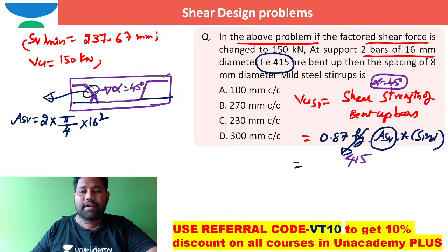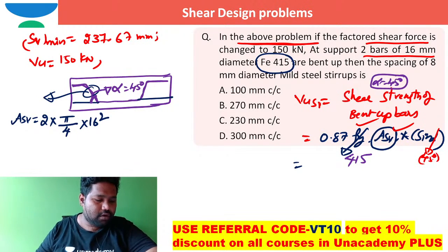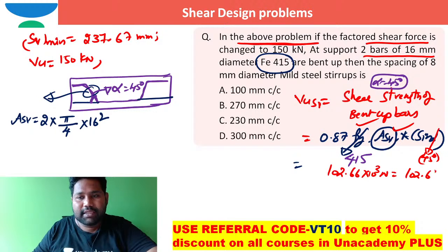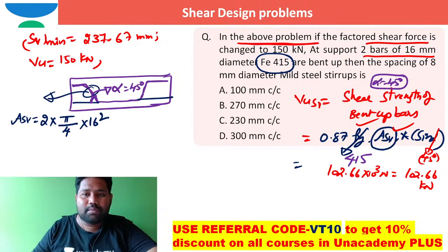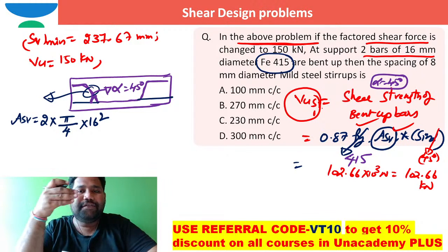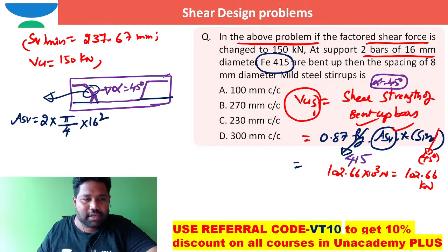Right. So ASV is known, Fy is known, sine 45 degrees is known. If you work out this one, you get 102.66 into 10 cube Newton, which is 102.66 kilonewton. But there is one more clause, brother.